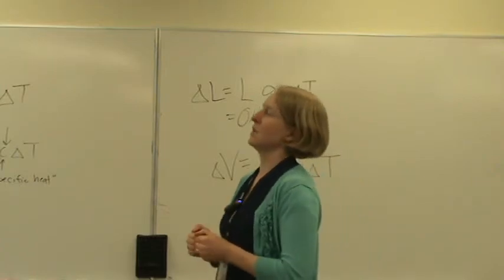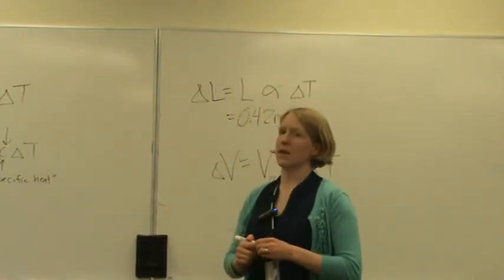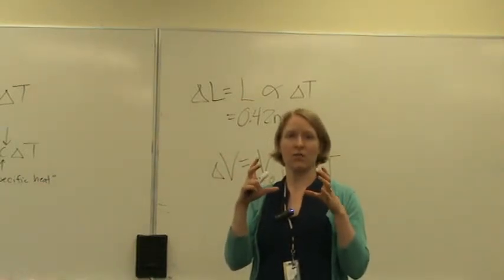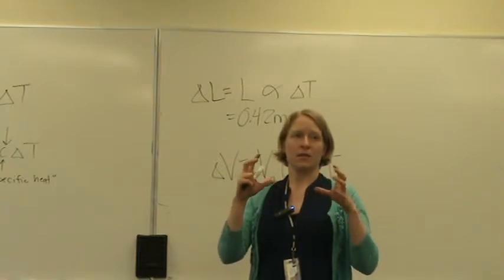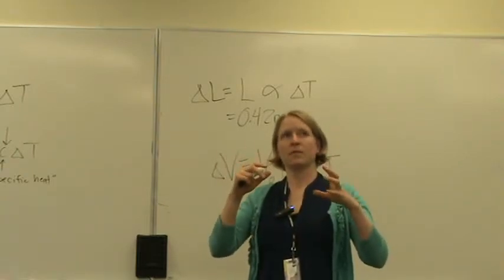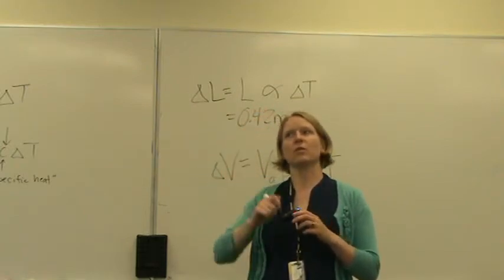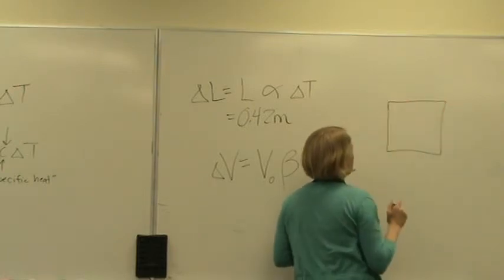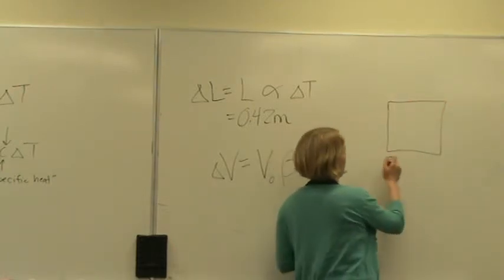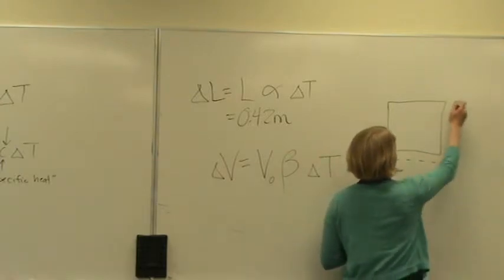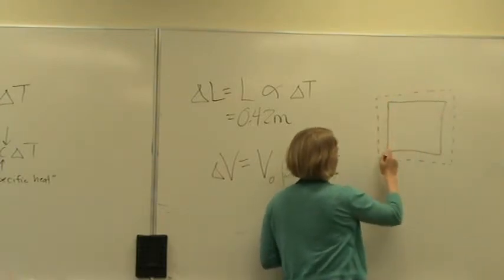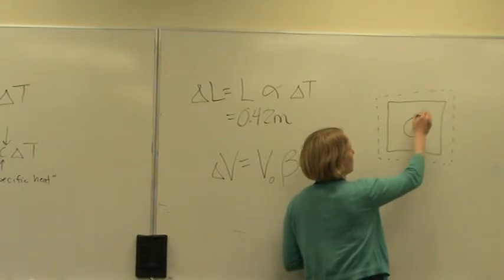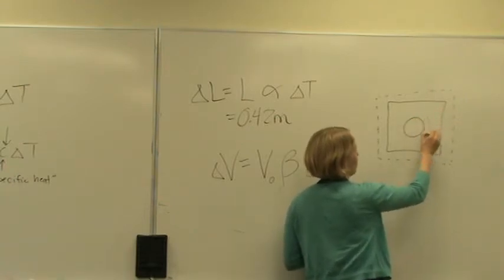One ball has less total volume of steel than the other ball. The answer is C, and the reason is that their outer diameter is the same. And so if you did calculate the change in volume, then this kind of goes back to the question we had last week, that if you look at a solid plate and it expands outward like this, and you had etched in the plate a circle, then that circle shape would be expanded out as well.